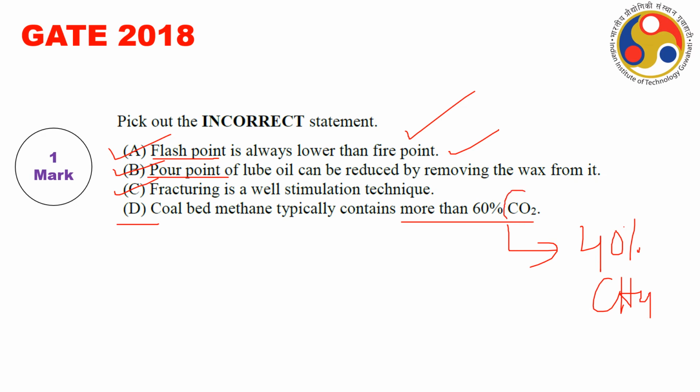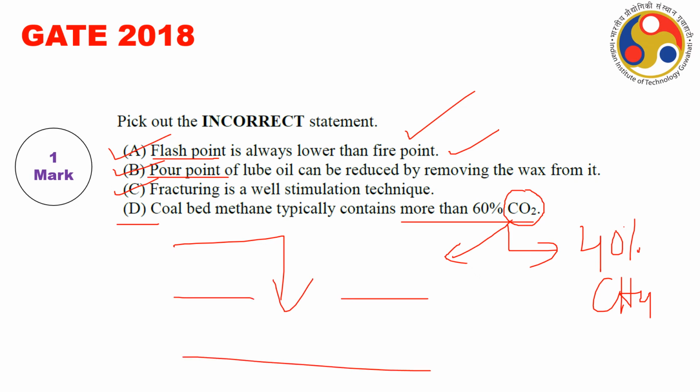Actually, CO2 is used for coal. As said in the last lecture, CO2 will be used to fasten the desorption process. It is called CO2 sequestration, or carbon dioxide capture and sequestration. When we inject CO2 into the coal reservoir, it will occupy the methane sites across the face and butt cleat system, so it will effectively push the methane towards the production well. This is done after the dewatering stage. It is a research topic and currently a burning topic.